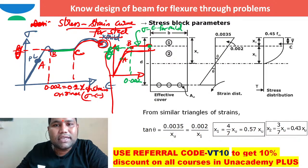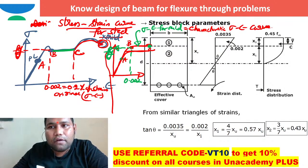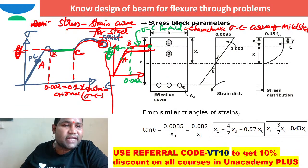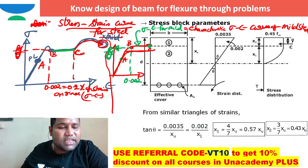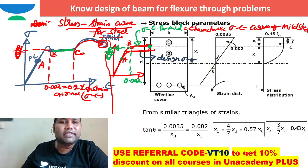So what is this? This is the actual stress strain curve, or I can say the characteristic stress strain curve of mild steel. How can you work out the design stress strain curve of mild steel? Characteristic stress strain curve of mild steel divided by the safety factor of steel, right? Can I write that one? So this is definitely the design stress strain curve. What is this design stress strain curve? It is the characteristic stress strain curve divided by the factor of safety.